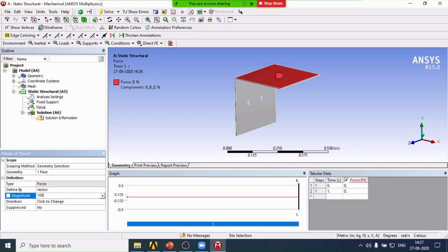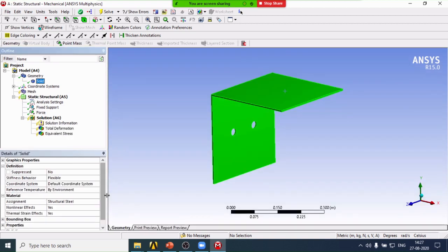So we have started the simulation with the initial starting parameter, that is the thickness, as an input parameter for my model. Output parameters I need to define. So I can go into the geometry. In the geometry I can click onto the solid, and here there is a bounding box, then properties. Here you can get the weight of it. So volume is there, and currently your entire plate weight is 6.9 kg. This is an output I want to measure. So I can now check this box which will connect to the output. That is the way you can do it.